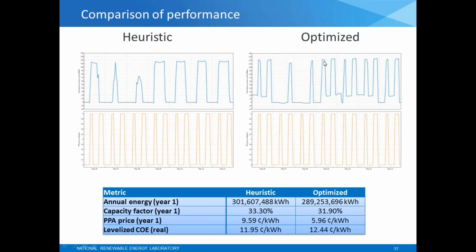It's anticipating, oh, I need this morning, I need this evening, and it's hitting much more of those high-value time periods than it was before. You'll also notice that at night, the system would just turn off. But here we actually are able to anticipate and say, well, I can run overnight at the minimum turbine output and then not have to incur my startup penalty the next day.